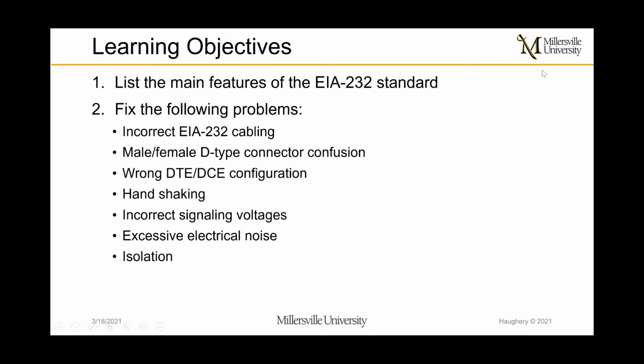The learning objectives today are how to fix the following problems: incorrect EIA-232 cabling, male/female D-type connector confusion, the wrong DTE/DCE configuration, handshaking, incorrect signaling voltages, excessive electrical noise, and isolation.